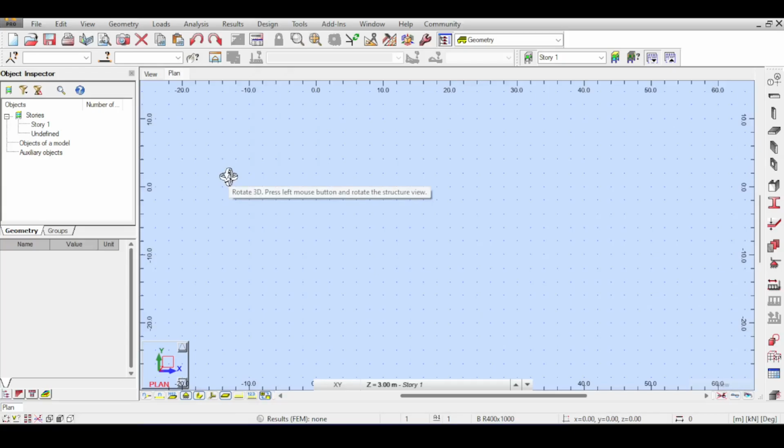So in this video I'll be talking about linear elastic foundation, basically elastic reaction on beams. This is a requirement for an idea I might tackle in the future, which is basically about stiffened raft foundations. I'm also thinking about raft foundations where you have some increase in thickness below the columns. This is not yet being done in Autodesk Robot, and I'm still struggling in my head to find a way to model those things.